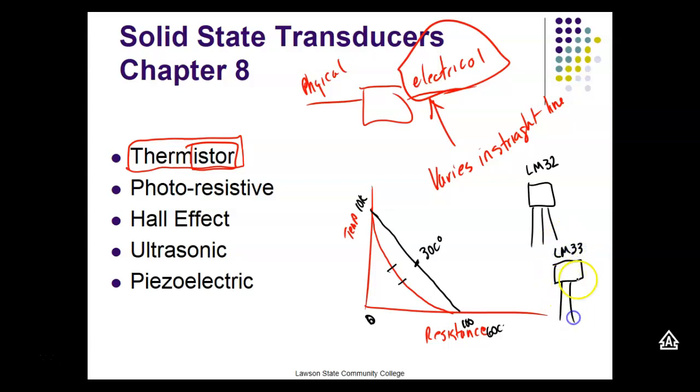We got one of them over there. One of them does Celsius, and the other one does Fahrenheit. So one of them's calibrated for the Fahrenheit scale, and one of them's calibrated for the Celsius scale. These guys are linear. But how do they compensate for the thermistor? They do it electronically, right? We could do it with a computer program real easy. All we got to know is the ohms per degree, and then what we would do is we would look it up in a chart. So these guys are real cool, guys. This is the thermistor. Let me find my parts.